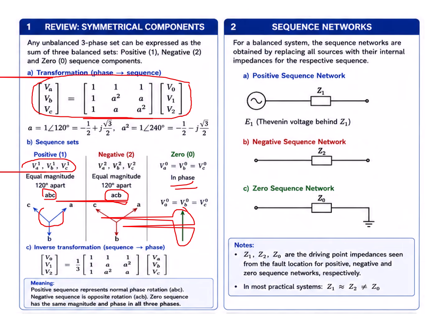It's very simple. But why we use this is that finally we will apply the sequence, or what you call the symmetrical component of a voltage, to a sequence network so that we can analyze the magnitude of asymmetrical current under different fault conditions.